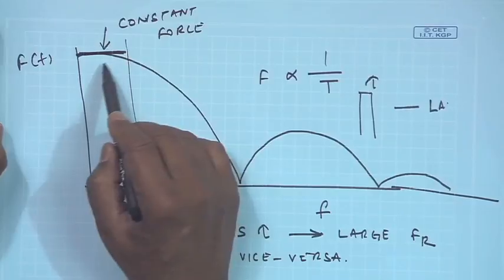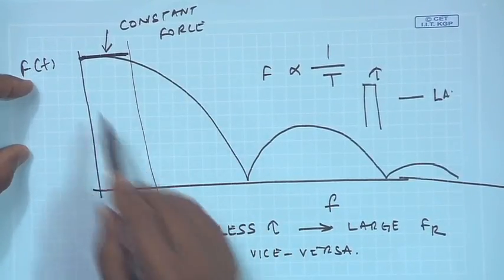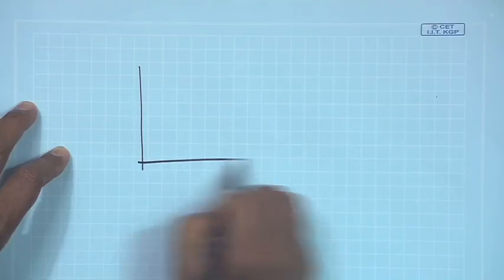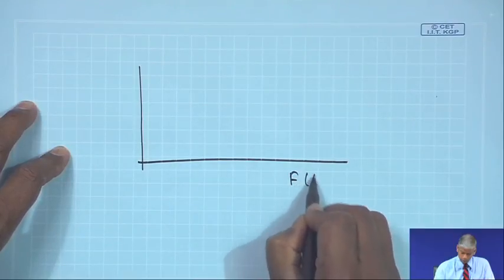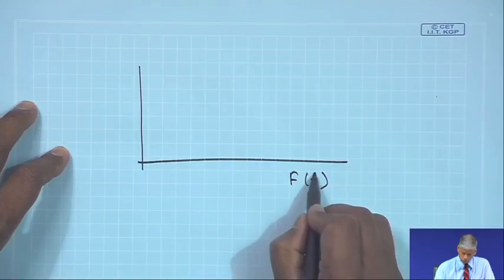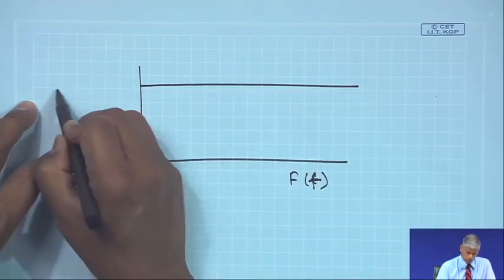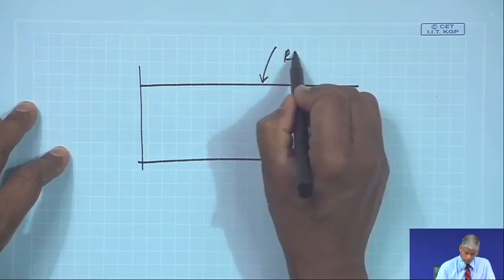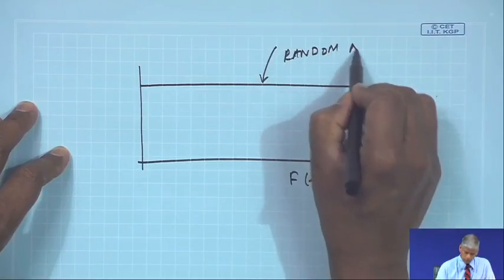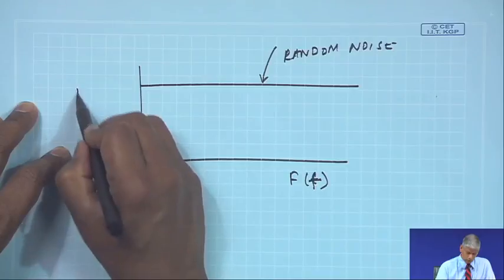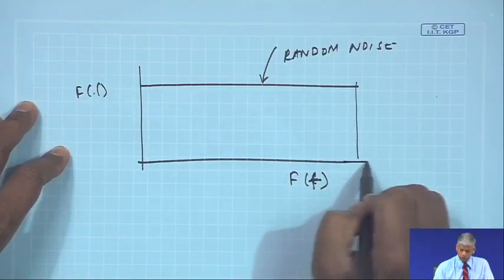Now, any response which I, well, I will come to that. So, basically I am generating frequencies till FR by giving an impact. Another method of excitation is this electromagnetic exciter, wherein I give a random noise. And this is generating a flat frequency to a large extent.